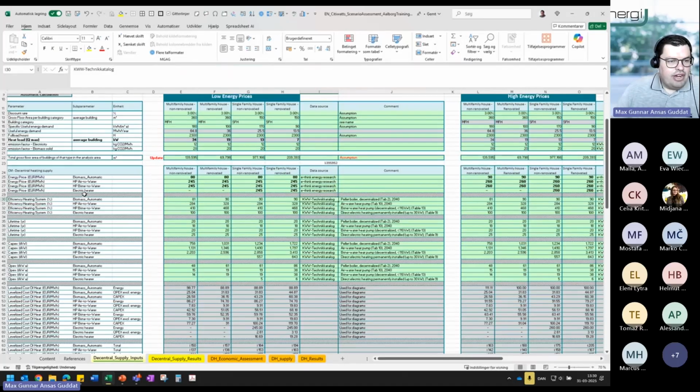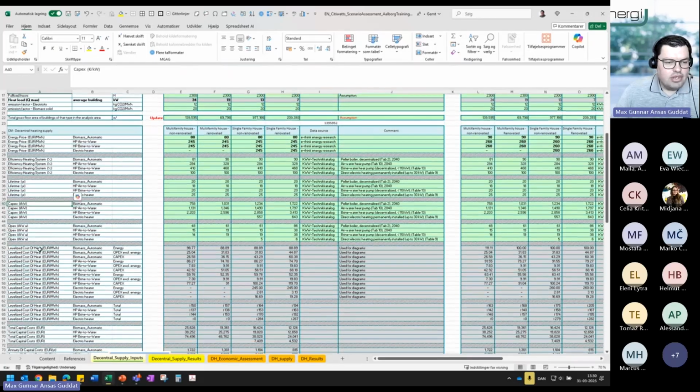The factors that we calculate for the different heat installations are of course the energy efficiency and the economy. Overall, we work with an energy carrier and the price for that. We work with the efficiency of the heating system. We work with the lifetime, so over how much time you want to depreciate the cost of a certain unit. We work with a specific investment, giving us a total investment in absolute costs, and then also the operational costs.